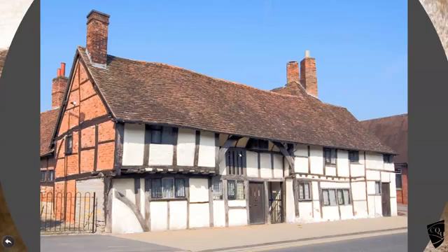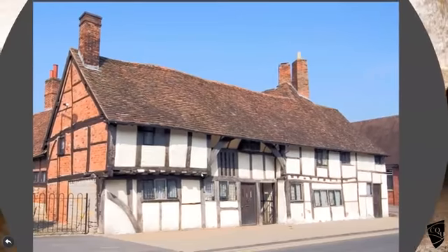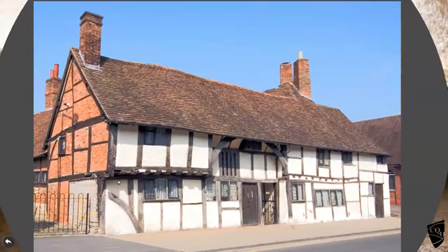That's an original window which would never have had glass in it in the first place. It's all timber. So it was traditional that you'd jetty, so you'd stick out past the bottom wall a little bit, and they're the floor joists of this room here, and that has a structural advantage because if you jetty out, it stops your floor bending so much. But at some point in time, they chopped them off here. Interesting, isn't it? But that's all timber.